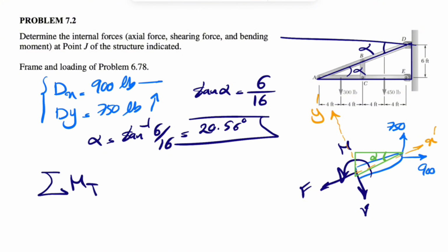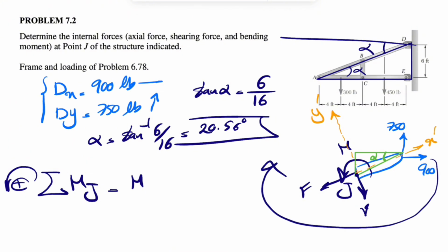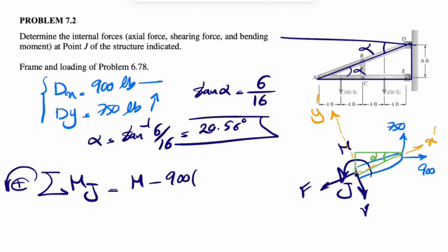Now we can go with our equilibrium equations. Let's start with the moment about point J, since we have the most unknowns at point J. Counterclockwise positive as always. So we have the moment, or the bending moment. The moment of the 900 about J, as we can see, is a clockwise moment, so negative 900 times...